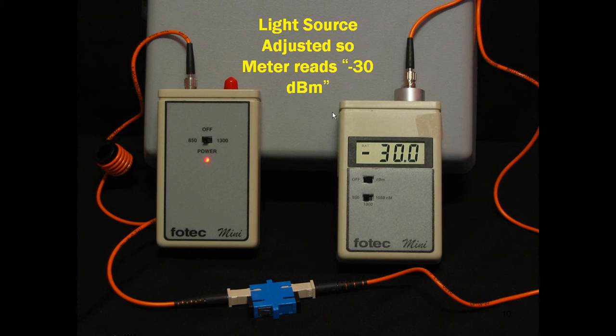The power's on. It's got an ST connector on the top, and it's got a jumper cable that comes down to an SC, Sam Charlie connector. This is an example of a hybrid test lead. If you're doing fiber optics, you're going to have to be able to test both the STs, the Sam Toms, and the SCs, the Sam Charlies. So if you have hybrid jumper cables like I have, you're ready to test either one. But this illustrates the SC connection.